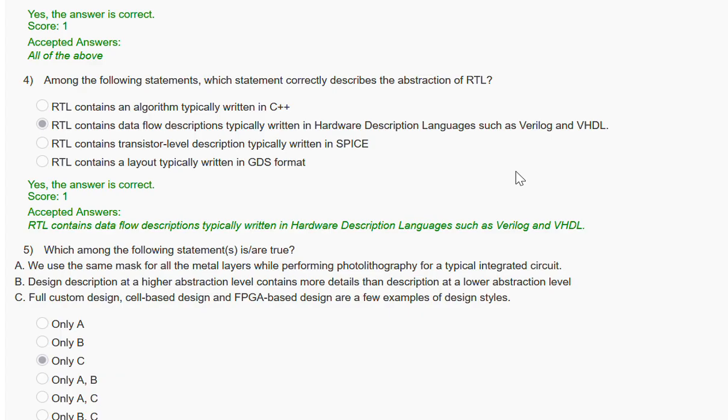In hardware, what we are saying is how my wires are going to be laid out, which will go as input to my logic gates and all. So it doesn't follow the procedural format that a C language follows. A C program will run in a sequential manner, but in HDL there is no such issue, because HDL means we are visualizing the hardware itself. So that's why it is different from C. The way of writing is somewhat similar to C.